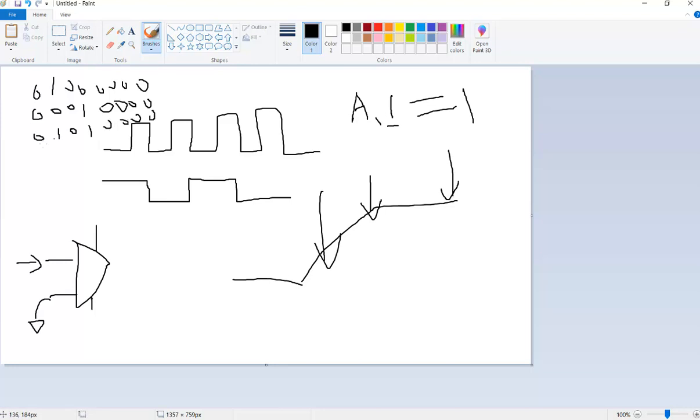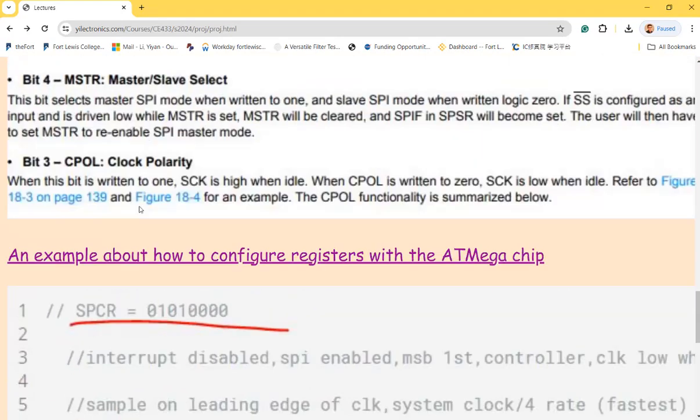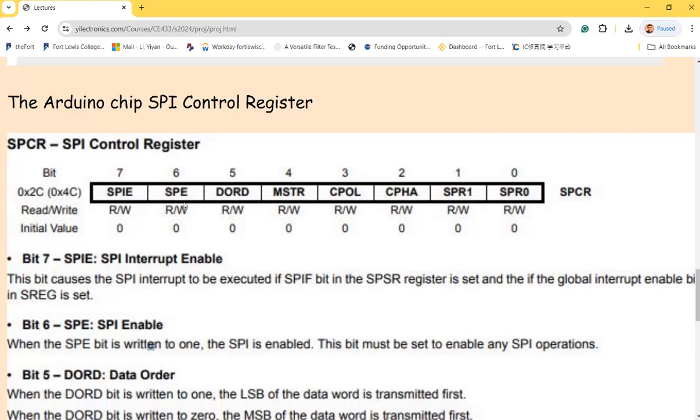So eventually, you are getting 1 byte as a configuration code for the register, and you assign it to this register. In that case, you are able to assert these 2 bits in that configuration register to get the job done. Similar operation with other bits as well: shifting a 1 to that location and doing a bitwise OR logic. Is that clear? Okay.